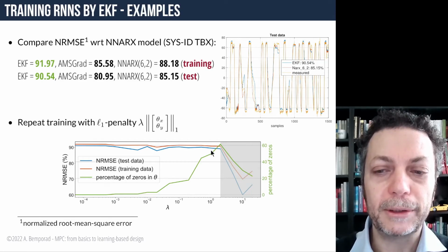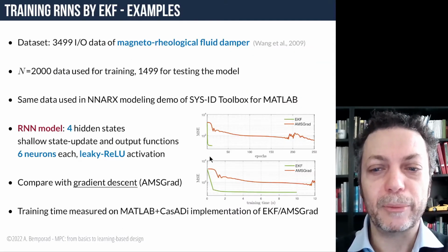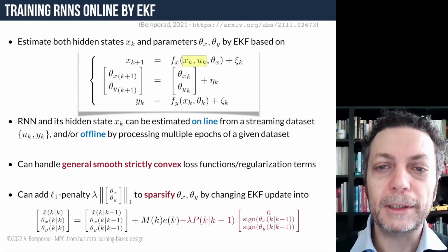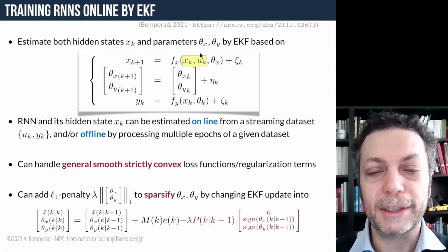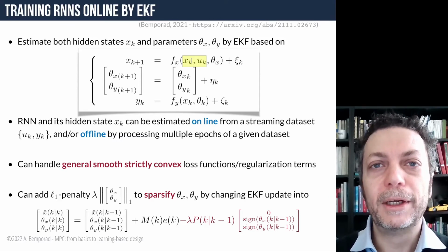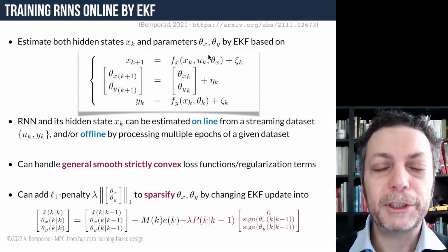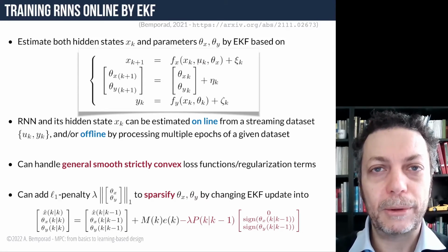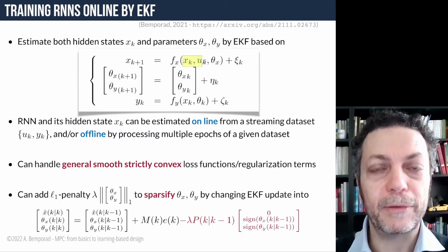I still get a good model, but I get a lot of zeros, which simplifies the model, because then the model equations will be simpler, in the sense that they will contain a lot of zeros. So if you take into account the sparsity of the model while constructing the model, you get a lot of advantage. First of all, you will have to evaluate simpler Jacobians, and in evaluating the Jacobians and in propagating the Jacobian matrices to construct the optimization problem, you can keep into account the sparsity so that you have zeros in the A, B, and C matrices.